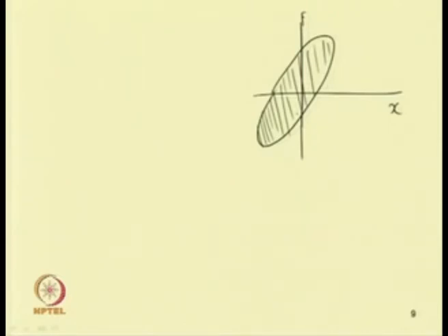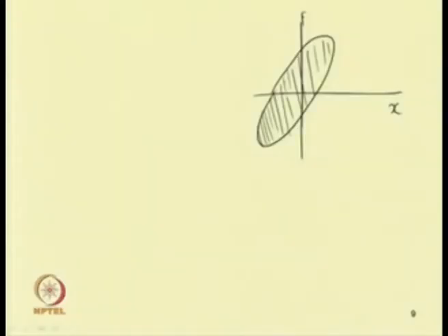This hysteretic damping may be due to the material, as different types of material possess this hysteretic type of damping, and in many structures it is due to the joints. So, one can have structural or hysteretic damping also. Hysteretic damping, material damping and structural damping can be combined to have nonlinear damping in the system. So, now we know we can write different types of damping present in the system, and they may be linear or nonlinear.